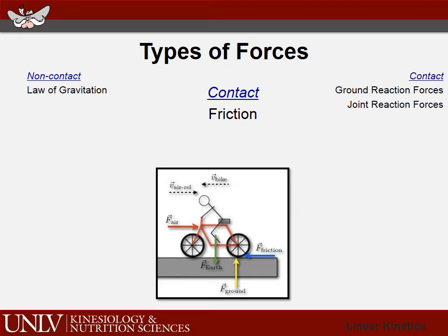Now think about what may be causing that. There's brakes. There's the tension at the hub of the wheel, depending on how tight you make the screws. There are many components that add to that resistive rotational friction. So when I talk about translational friction, I'm talking about the one occurring at the ground with the blue vector. But rotational is friction that's causing the wheels not to spin or rotate easily.